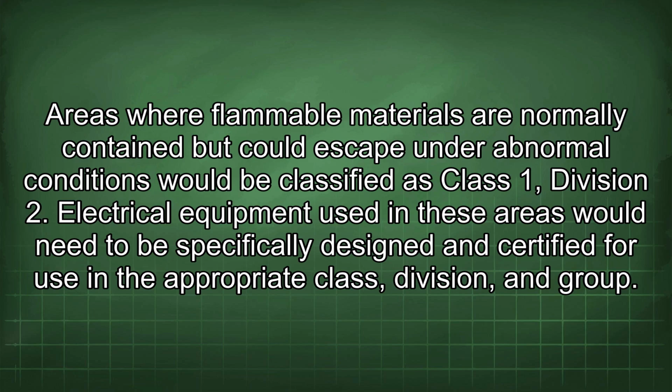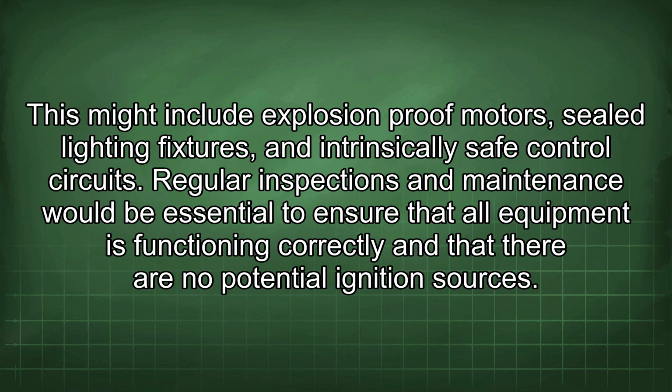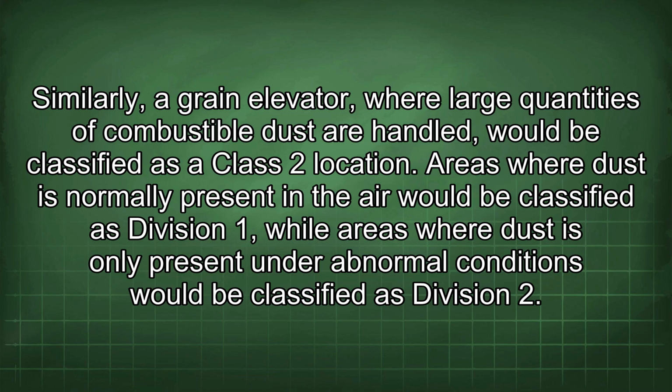Electrical equipment used in these areas would need to be specifically designed and certified for use in the appropriate class, division, and group. This might include explosion-proof motors, sealed lighting fixtures, and intrinsically safe control circuits. Regular inspections and maintenance would be essential to ensure that all equipment is functioning correctly and that there are no potential ignition sources.